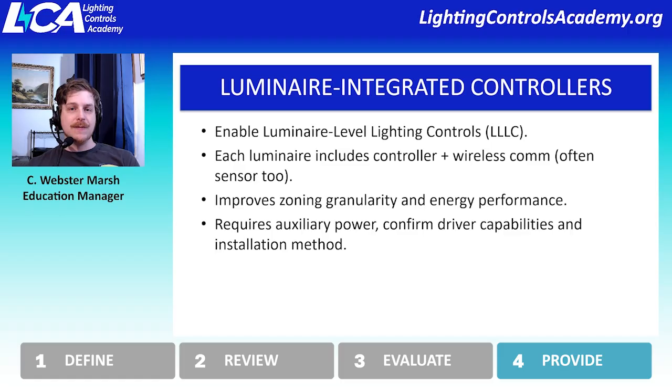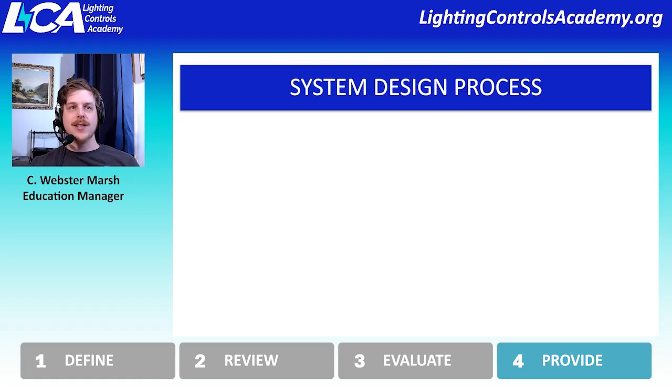Or it might be field installed, meaning that the light fixture manufacturer sends the fixture to the site, the lighting controls manufacturer sends the module to the site, and the contractor will install that device in the fixture. And it's the second one that really could run into issues if it's not carefully planned out and that auxiliary power source hasn't been provided. The drivers might have to be swapped out, or the entire fixture might have to be swapped out, and that would be a very costly change in the project.